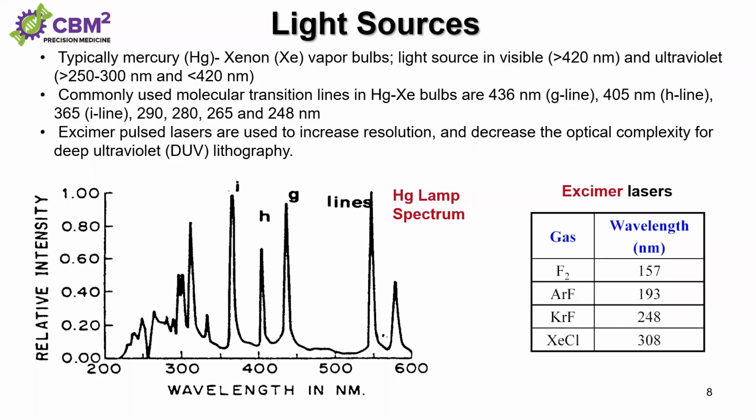These days people use deep ultraviolet lithography and extreme ultraviolet lithography to make patterns smaller and smaller. But the problem is, if you use a different light source, then the entire equipment has to be redeveloped, so the equipment is a lot more expensive to enable photolithography with DUV or EUV light sources.